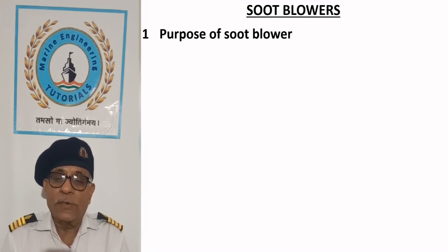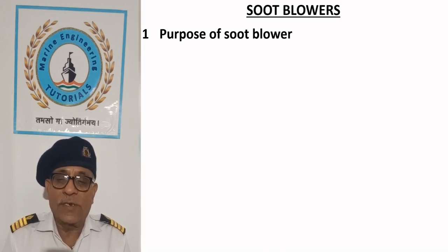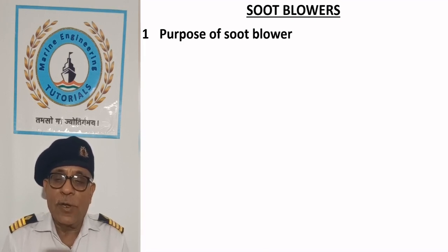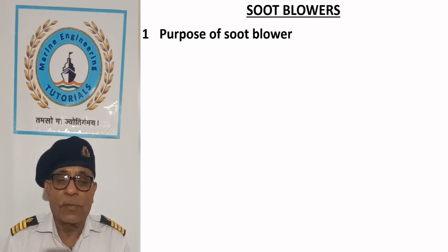Their main purpose is to maintain the heating surfaces on the gas side of a boiler in clean condition and prevent heavy buildup of deposits, which can lead to corrosion and uptake fires, in addition to a drop in boiler efficiency due to poor heat transfer.